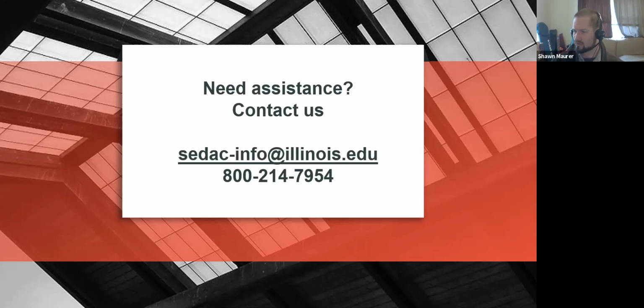We did have one more question come in before we wrap up. Are there different levels of efficiencies for HEPA filters for in-room purifiers? A HEPA filter itself has a specific filtration efficiency to qualify as a HEPA filter. The main thing to consider with those units is the clean air delivery rate, which is a documented component of those systems.